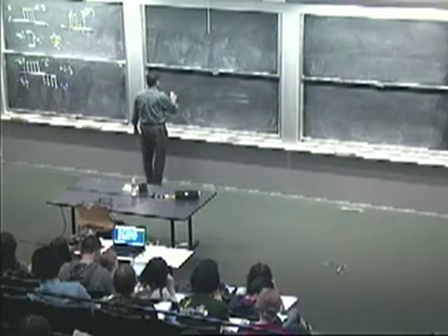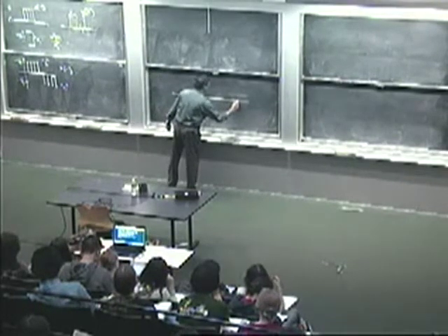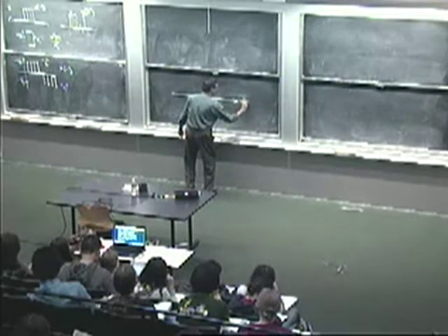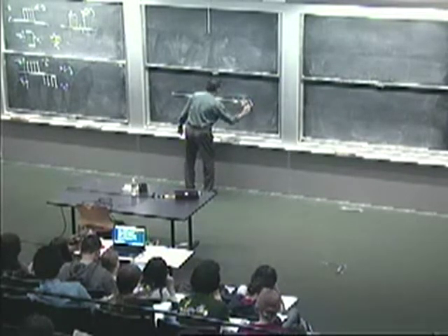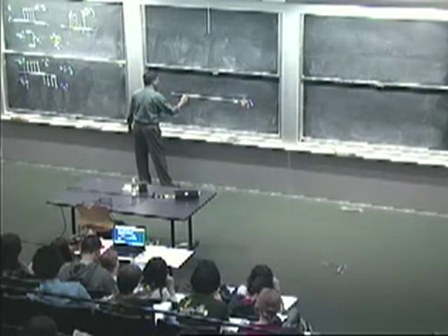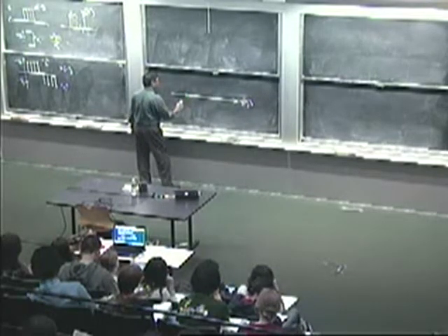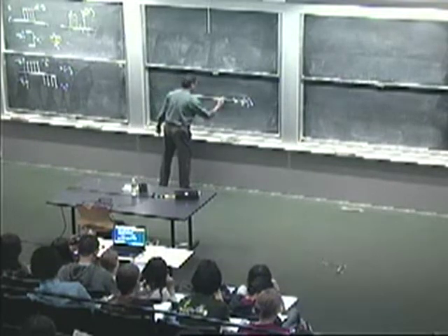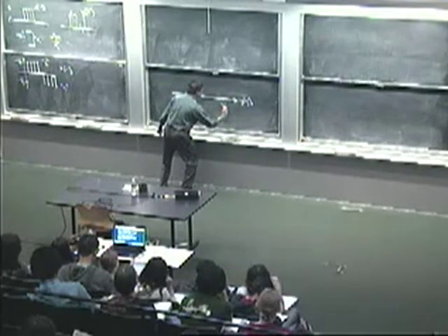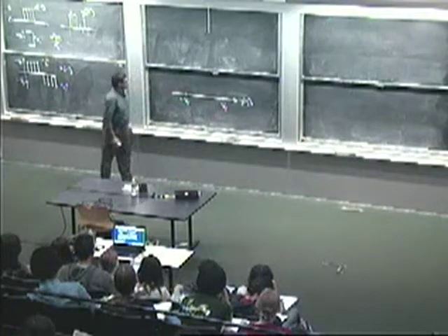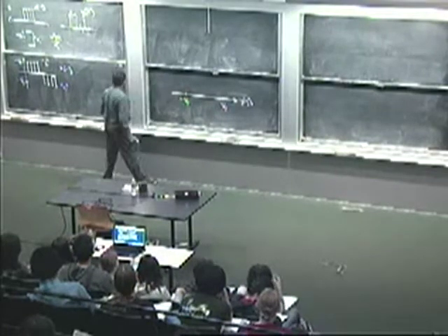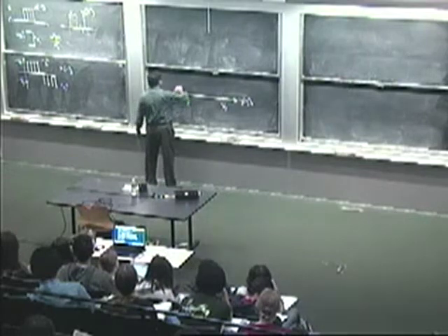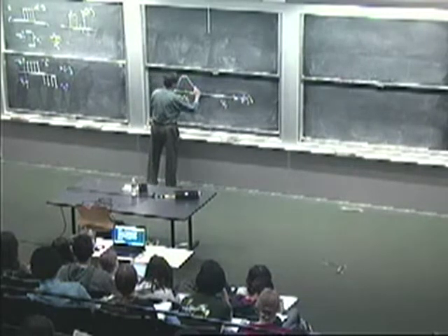So if I draw a picture that's turned sideways here in terms of the received signal, I might get something centered around minus Vp or something centered around Vp. If a minus Vp was sent, then it's got noise added to it. The noise has a Gaussian distribution.